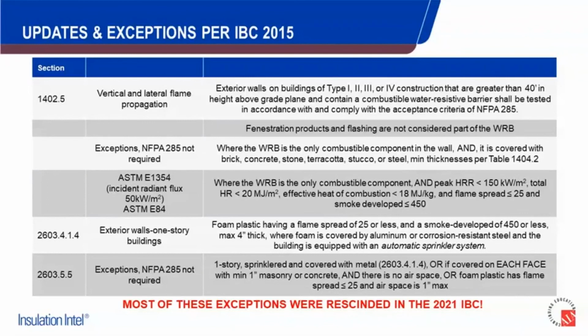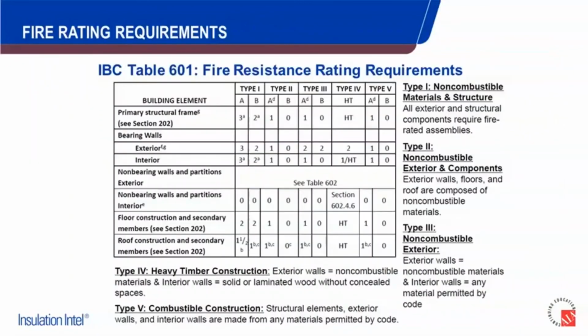So as that code begins to get adopted throughout the US, your ability to, I don't want to say skirt, but maybe find an exception to NFPA 285 is getting smaller and smaller. So it's going to become more difficult to avoid having to meet compliance of this test.